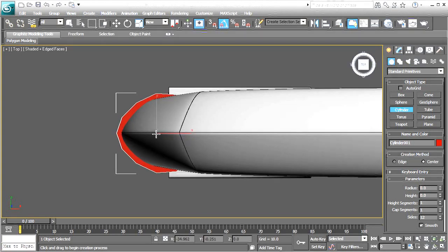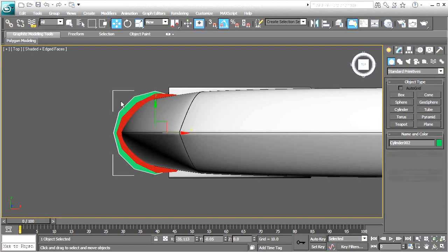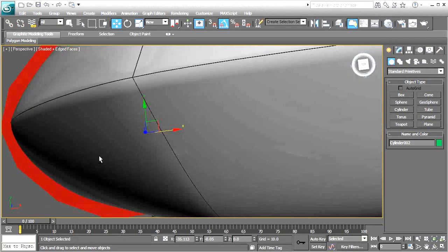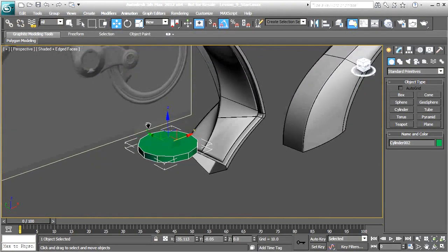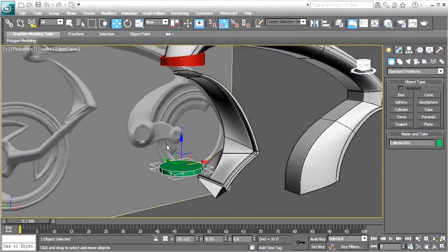Okay, so let's go ahead and build this cylinder out, and I'm just going to get a rough size here because I can size it up. Now remember, you need to get your height so you can see how it's fluctuating that value. So we need to click one more time to end that, and then we'll right click to end the cylinder creation process. So I'm going to switch to my perspective view. I'm going to hit P on the keyboard this time, and now I can orbit around that. So we're seeing some keyboard shortcuts here that's really speeding up our production process.